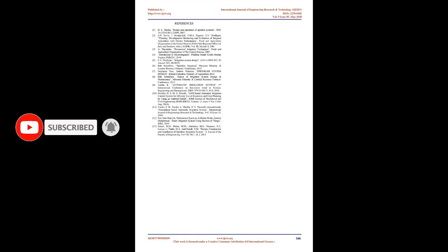10. The pump house should then be started. The irrigating unit will then start to work. As it irrigates, it winds the cable on the winch and in the process, it pulls itself on the cable. Once it reaches the predetermined distance near the opposite end, it automatically stops moving and irrigating. If a standing time is allowed for, it stops moving but continues to irrigate during the standing time.